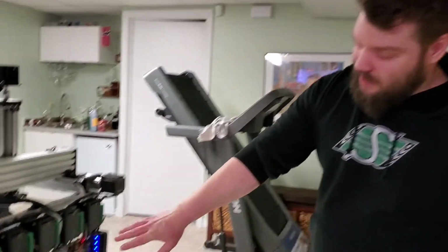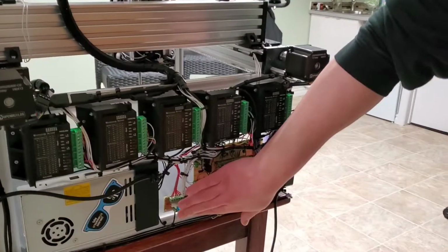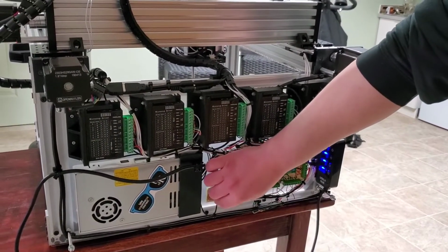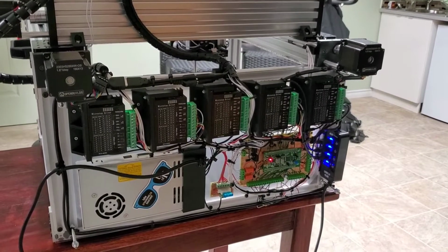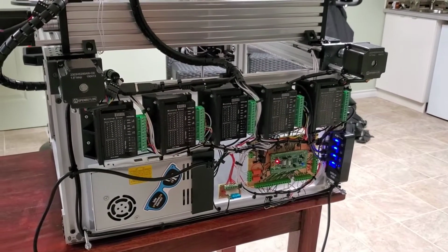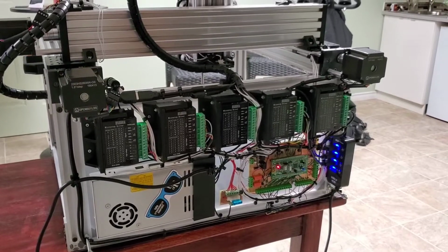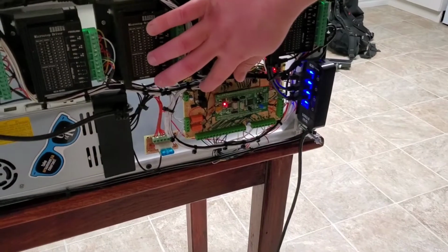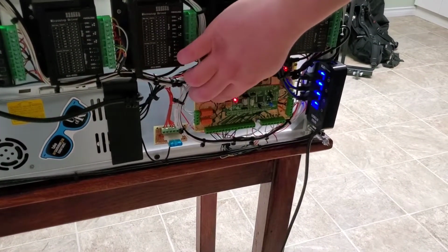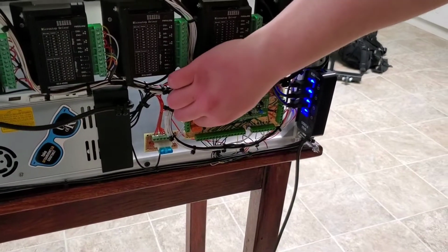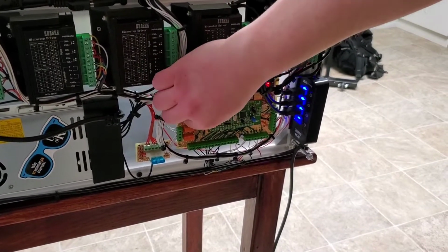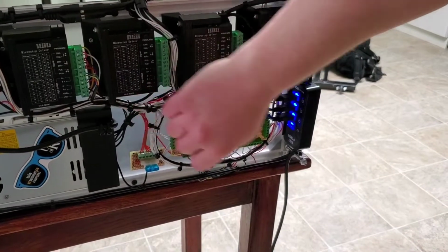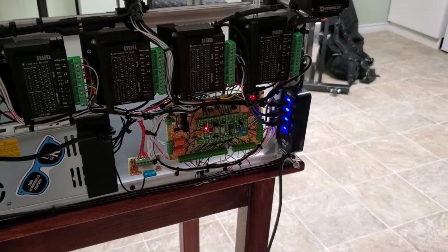I'll touch on the little bit of isolation here between the protoboard and our power supply. So we have the fuse right there. If we ever draw more current than we're expecting, that's going to isolate our main circuitry there. Part of the power supply subsystem that Matt touched on a little bit ago would be these Recoms here. So we have a 12 volt switching regulator, our 5 volt switching regulator, and we have a linear power regulator, which is our 3.3 volts for digital logic.